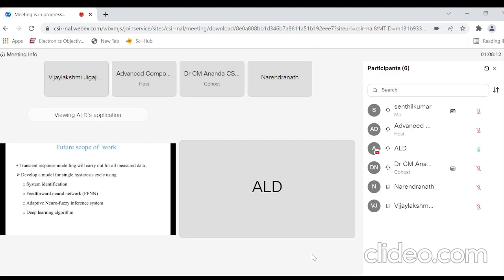Now you mentioned that the Hamilton model is not predicting at lower frequencies. My opinion is it is a good model, but your loss factor, if you consider, is 0.1, meaning it is going above the 10% range. That is the reason at lower frequencies in any fatigue cycle, tension and compression mode, when it is going up the controller will take the full load, PID. When it is coming down, it is not taking the load. Basically, you have a loss factor of 0.1. You should investigate if you can reduce the loss factor still lower and try to match the data. That is my suggestion. Okay, sir, I will keep it in mind.